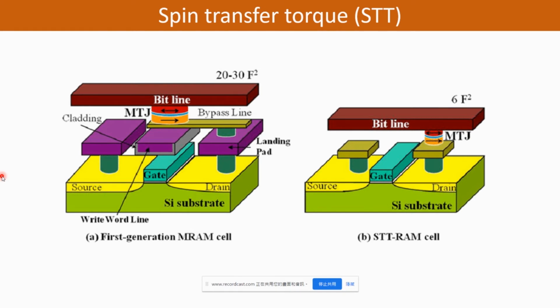To control the writing in the memory of this conventional MRAM, we need to control the current to flow through a certain bit line and word line. Because when we turn on the bit line, all the MTJs under this line will get the same magnetic force in a certain direction.